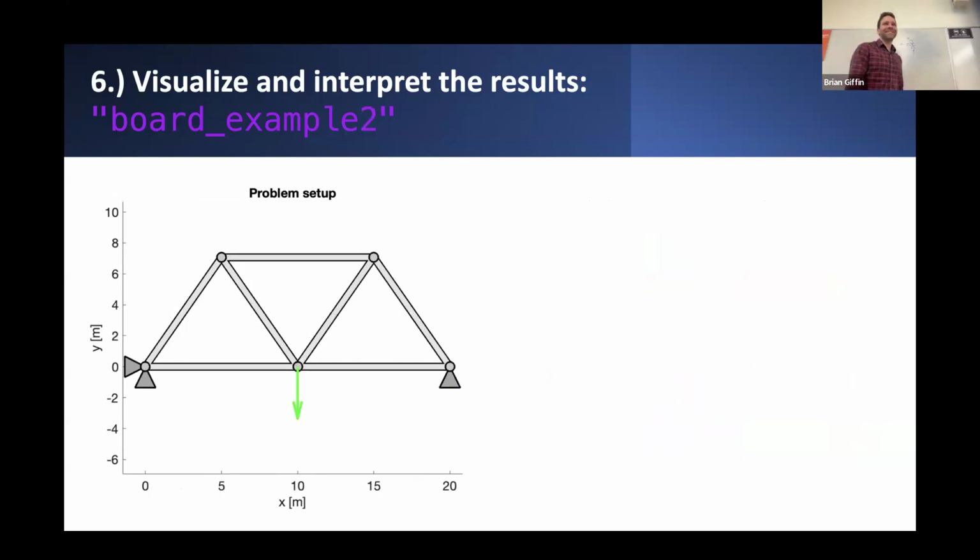All right, what about this one? This one maybe is a little bit easier. What are the internal forces for all the top members? Let's say these three members on the top of this truss. Compression. Yeah, and the bottom members? Tension. And then these internal members? Could be compression. Well, that's a good question. What do you think? If you had to choose one way or the other, tension or compression, maybe one's tension and one is the other.